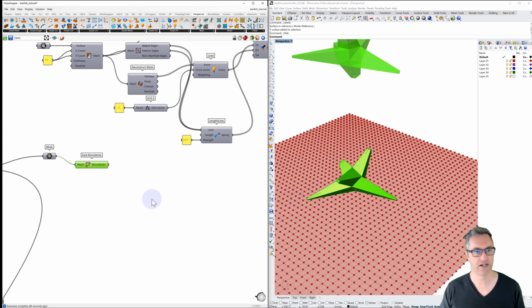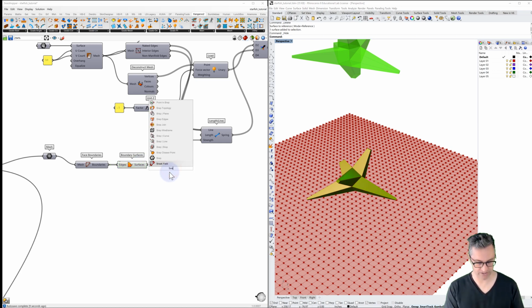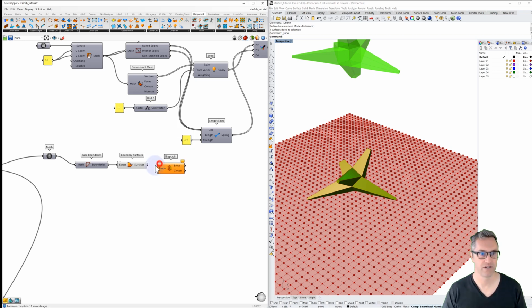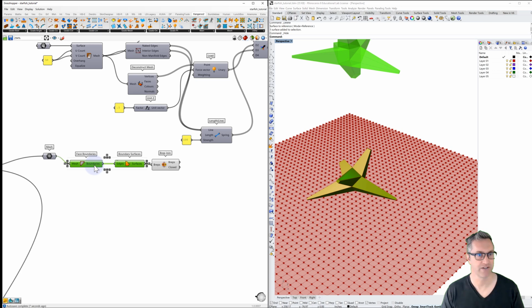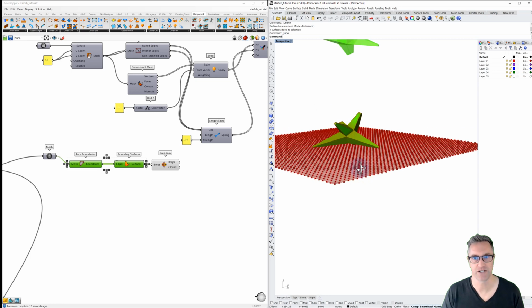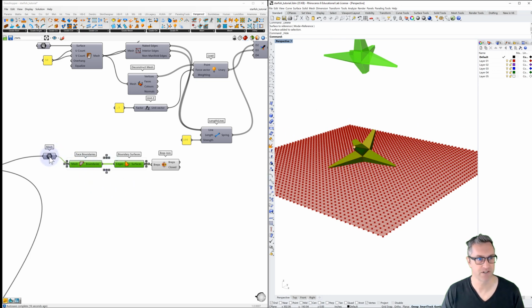So we're going to take our face boundaries, then we're going to make boundary surfaces from those. Right now we have a whole series of trimmed surfaces. Now we'll brep join these. So what we end up with is now a brep. And the reason why, again, that we had to do that, why we can't go back to our earlier brep, is that this was a mesh from the simulation, and we just, through these couple of steps, changed this mesh into a brep.